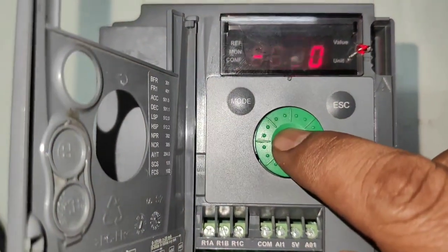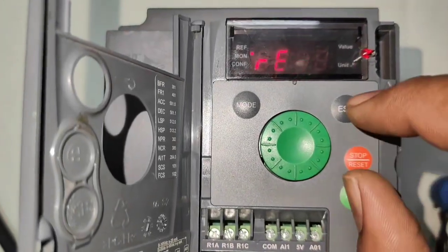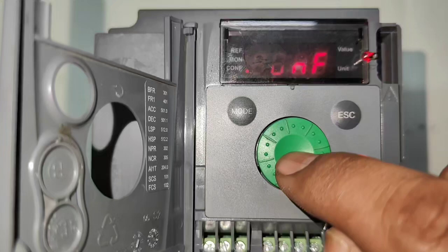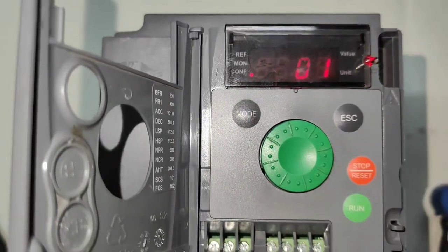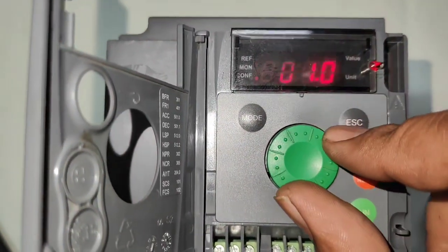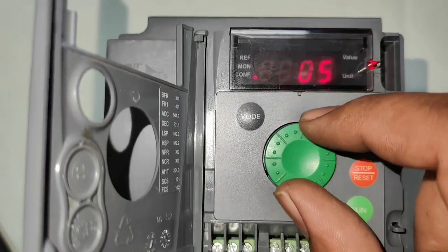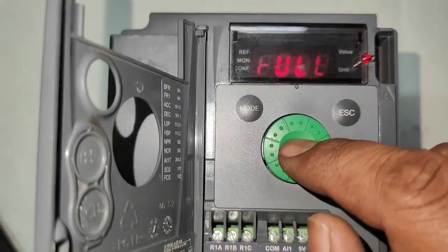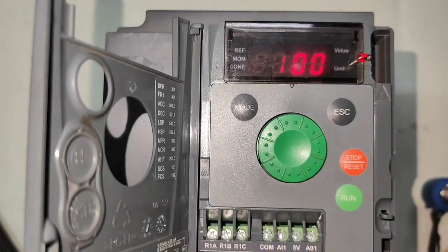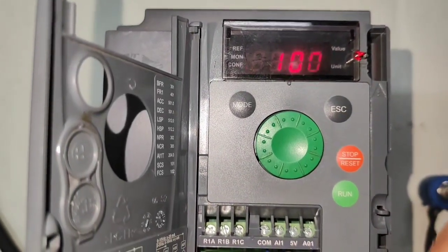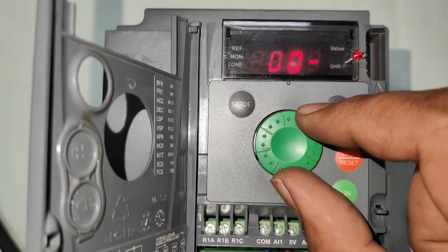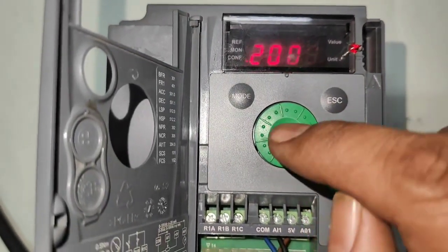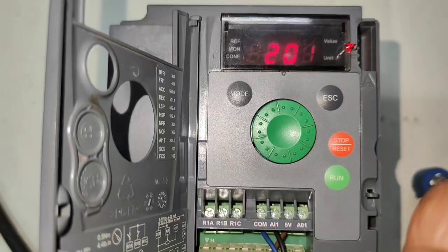For parameter setting, first we press the dial key, reference, just rotate, and it's configuration. Again press the dial key, just rotate the dial key and find full parameter setting. So just find full, again press the dial key, it's the 100 group. First we enter the 200 group, so just rotate one more time, 200 group, and just enter. The first parameter is